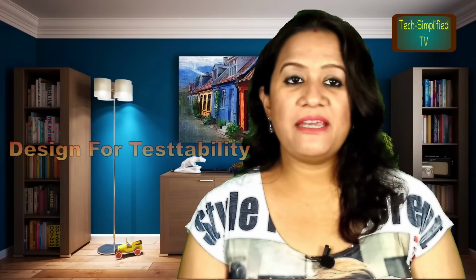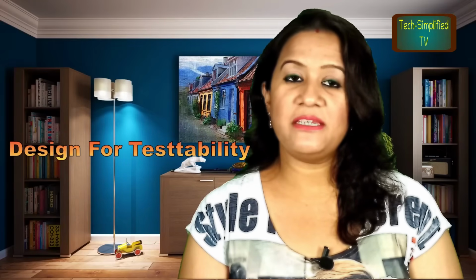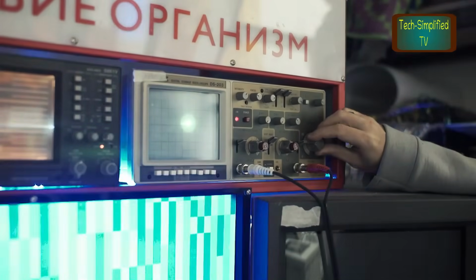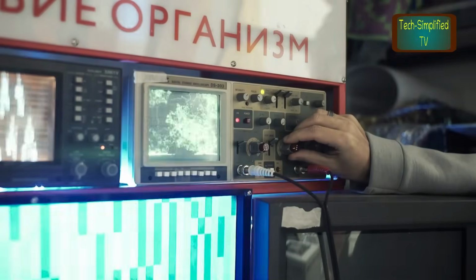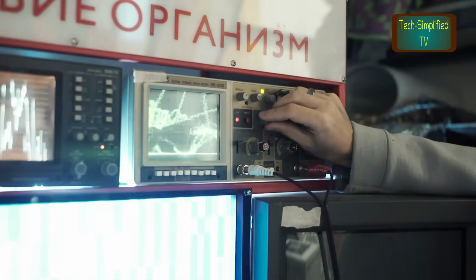Number 4 is DFT. The above mentioned 3 verifications are pre-production, whereas DFT is done after production of the chip. During the design process, extra logic is put in the design which is actually used to do post-production testing. The purpose of DFT is to validate or verify that the end product does not contain any manufacturing defects.